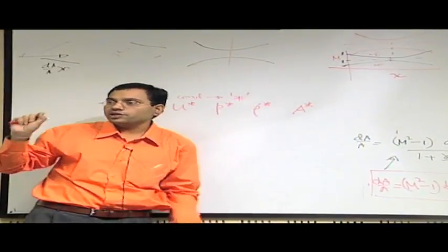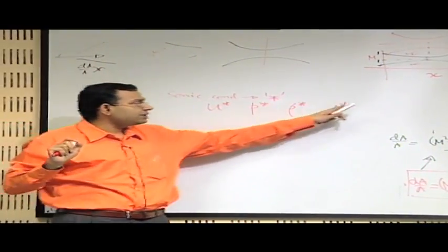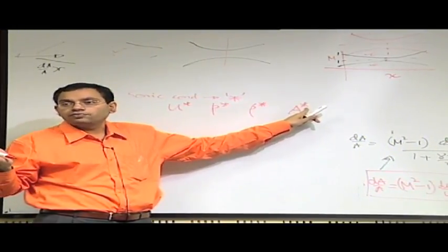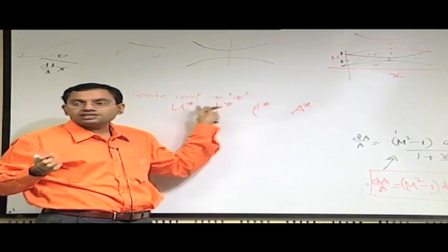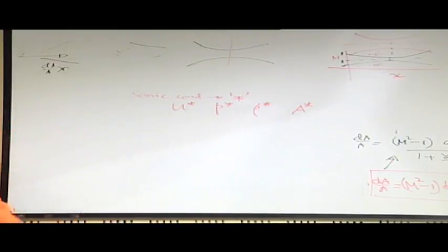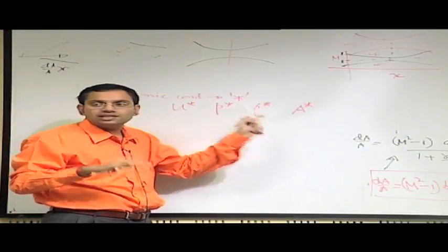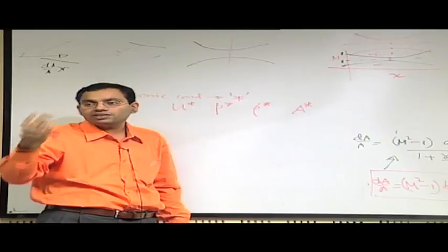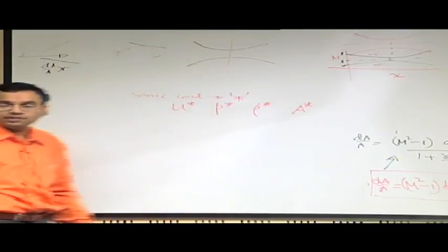So corresponding to each state there is a corresponding star quantity, and if you see tables of properties of compressible flows, these star properties are there. So these are very important reference quantities, not that these values have to exist in the particular flow condition, but these are reference quantities with respect to which other quantities may be expressed.